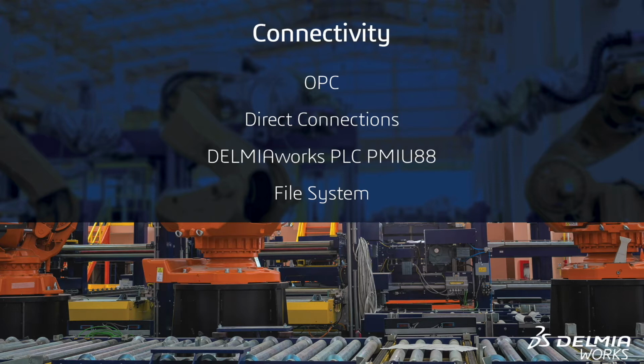The OPC server is then a conduit that can communicate data continuously among PLCs on the shop floor and real-time process monitoring. A leading OPC server is KEPServerEX, which DELMIAworks has selected and fully supports. KEPServerEX leverages OPC and IT-centric communication protocols such as SNMP, ODBC, and web services, and offers the broadest